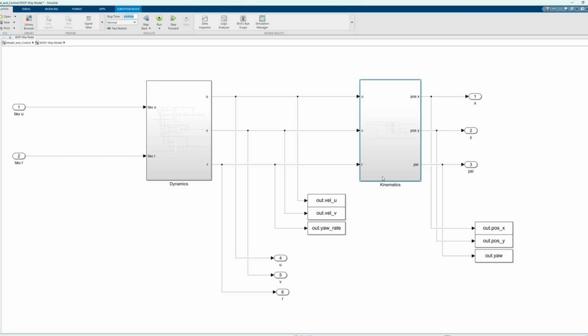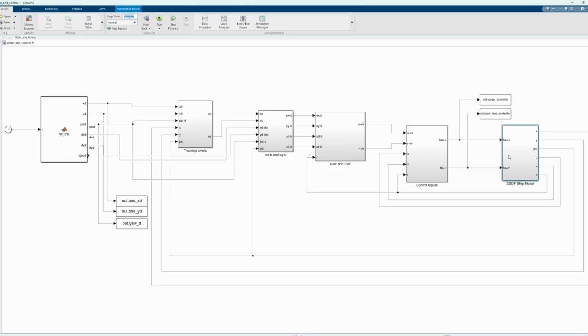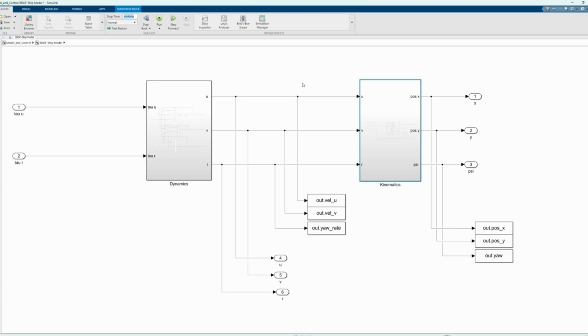You can also do state estimation, because sometimes sensor outputs are not good. So with state estimation, you can modify this controller. Nonetheless, the basic concept which I wanted to teach you in this course is that we need virtual controls for the kinematics. If you look here in the kinematics, there is no control input, but the dynamics has two inputs. So we need to design these two inputs in such a way that they control u, v, r as a controller to our kinematics. So that's all.